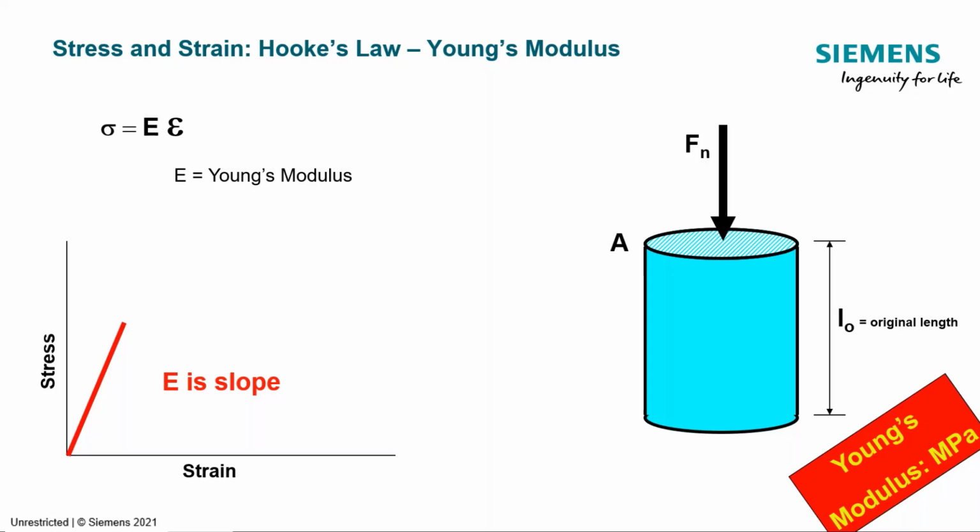And the conversion is easy, but it's screwed up a lot, because this is in terms of microstrain, and this thing is sometimes given in gigapascals. So when you do this calculation, just be careful that you're getting your zeros right. If you're off by a factor of 10, it's really screwy. We see this formula messed up a lot. It's a simple formula, but it's easy to mess up. Just be careful. We'll see a factor of 2 is a really big factor in fatigue. So a factor of 10 is outrageous. So just be careful of that.